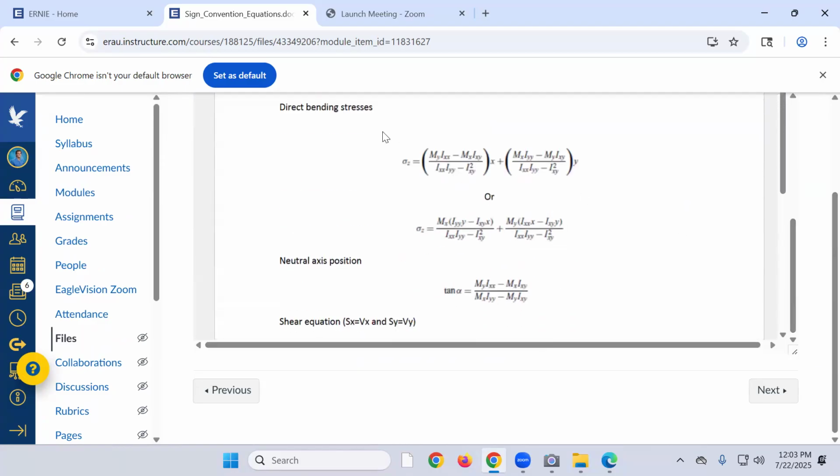If you look at this equation here for the stresses, what do you think is the most important quantity to properly model? The loads are going to be the same in FEMAP as in the analytical, correct? So what is the other variable for which everything is a function? The moment of inertia.